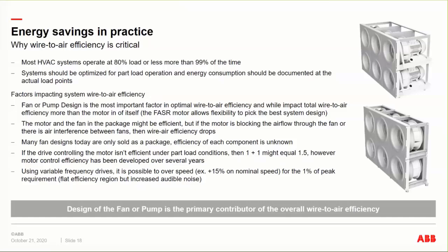Picking the right design, where the motor is located in the airstream, is it blocking the airflow, etc. If it's a package design, really the efficiency of each component isn't known. It's just the overall package efficiency. So it leads to maybe a little bit less innovation in design. You have to look at the drive converter. So is the drive controller efficient at those partial load and partial speed points?